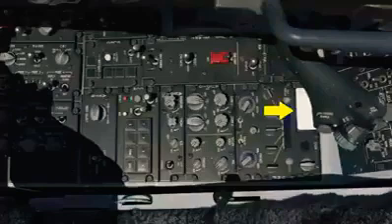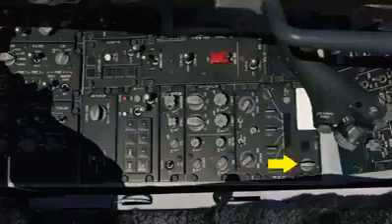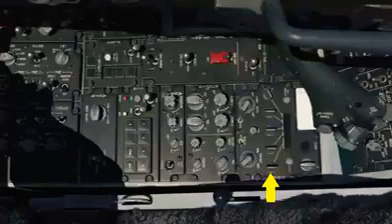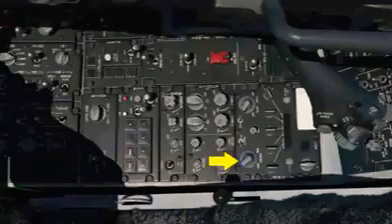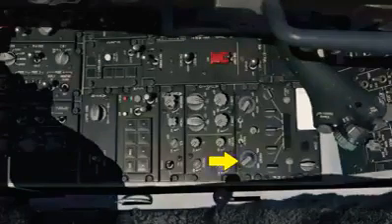This includes a door with a preset channel entry button behind it with the selected preset channel to the right of the door. To the right of that is a knob that selects the preset channel. In the center of the panel are controls to set the frequency with the input dials in the display window. Along the bottom is a function knob to control radio power and mode, a tone signal button, the volume knob, squelch select, a mode select knob for manual, and preset guard frequency of 243 MHz.